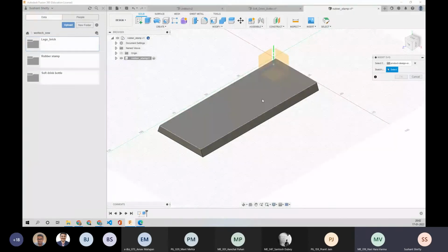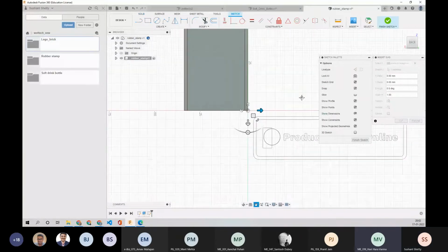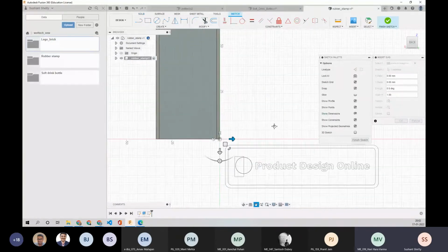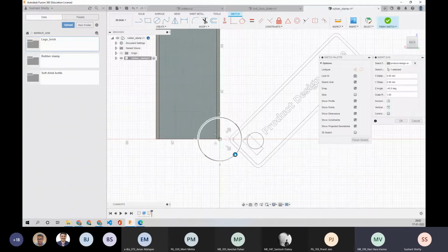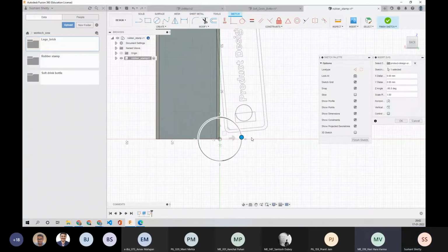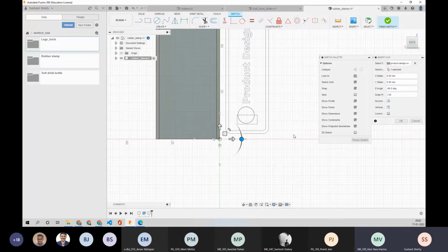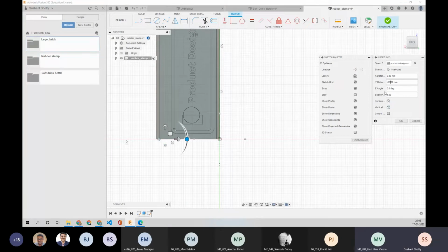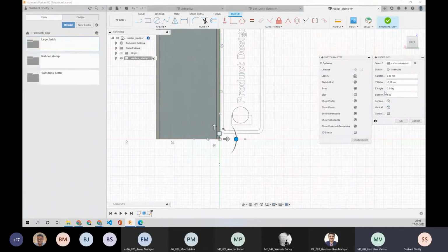I'll select this as the sketch plane, and if you see here, it has come out outside this thing. There's this rotation tool which is already available. All I have to do is place it at this point. Now it's along the y-axis, so I'll have to change the y distance to, let's say, -30. It's come inside. I'll just keep this to -32. Okay, I think it's almost equal on both sides. I think it's 32.5.